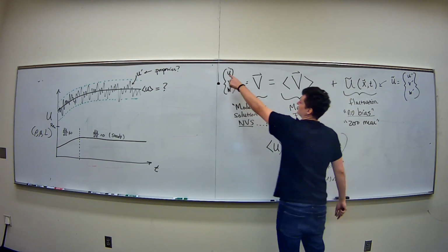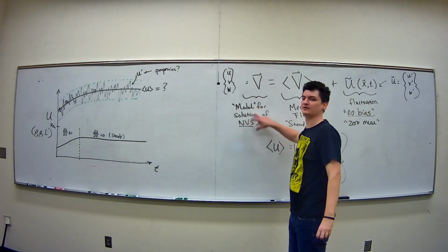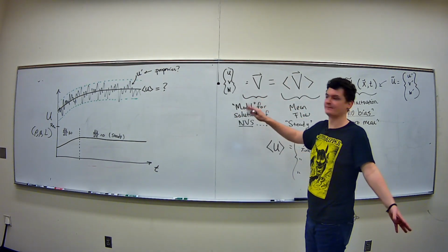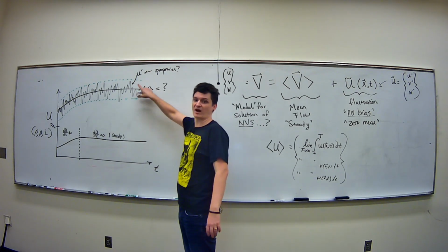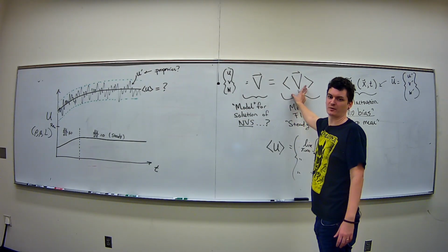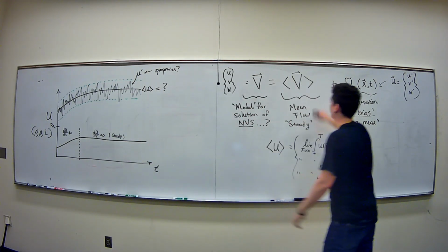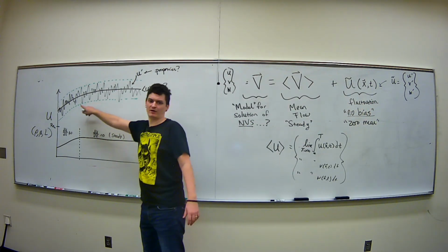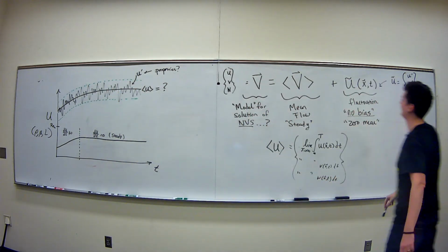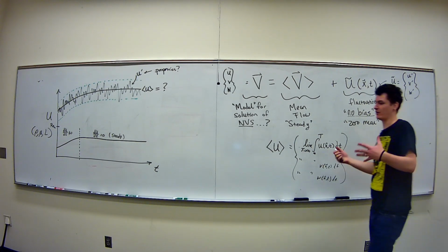Before, the Navier-Stokes equations were modeling the actual u, v, and w of your velocity field. This model of the solution is now decomposed, based on experimental evidence. Whatever the solution is, I can take a mean of it. That's the process of me on my computer saying, give me an average line there. That's what you're doing on this term right here. You're solving the Navier-Stokes equations, i.e. performing an experiment. You're creating a mean flow. You're saying, computer, tell me the mean of this flow, as Picard would say. And then you have this extra unknown thing. The only thing you might know about this is that it has a 0 mean.